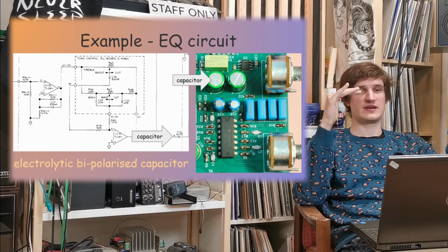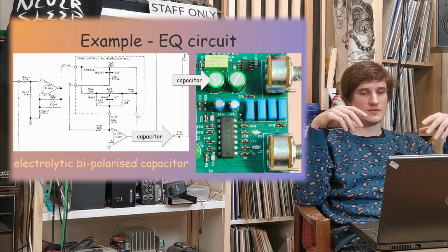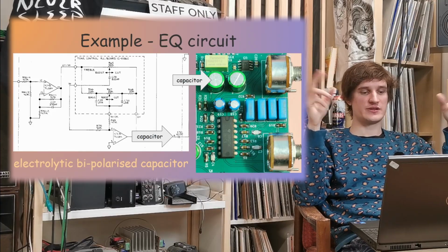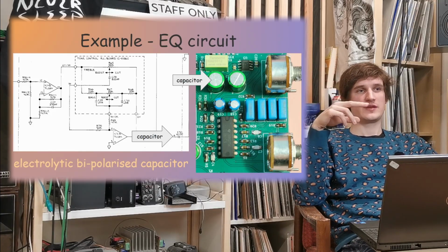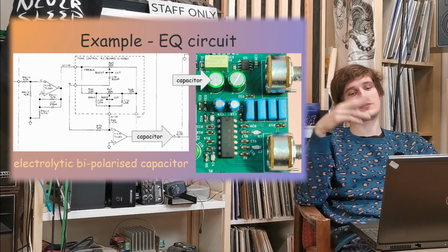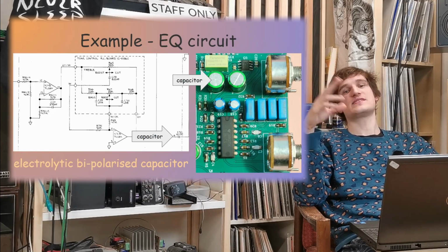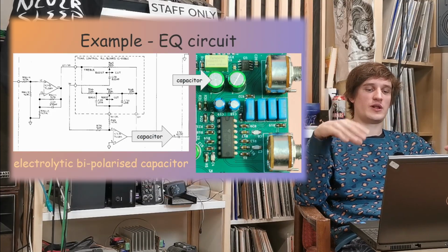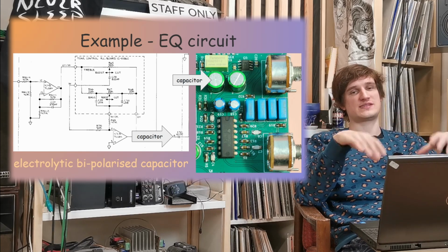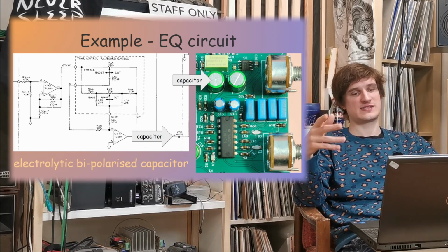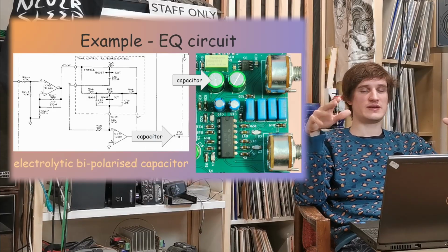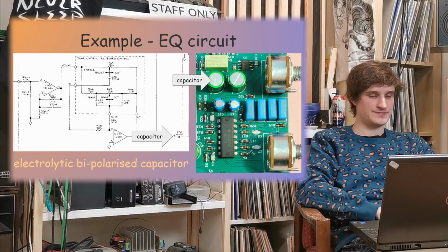When you have current flowing both ways, you want symmetrical behavior, and a polarized capacitor represents less symmetrical behavior, and it can introduce some non-linearities and distortion.